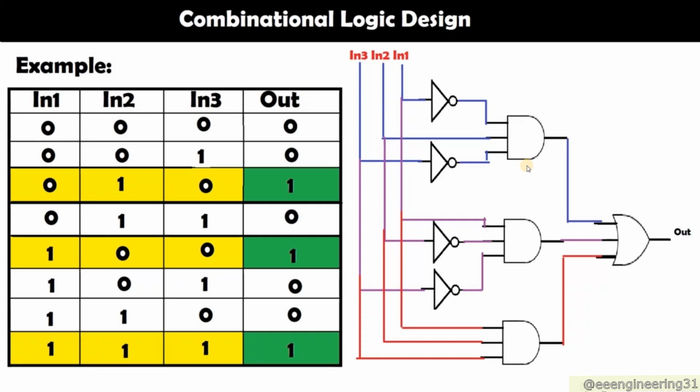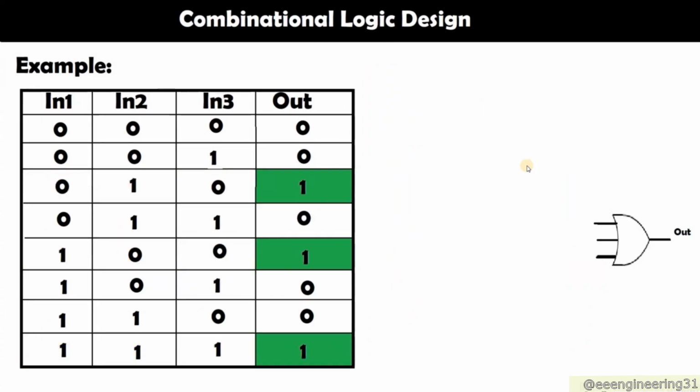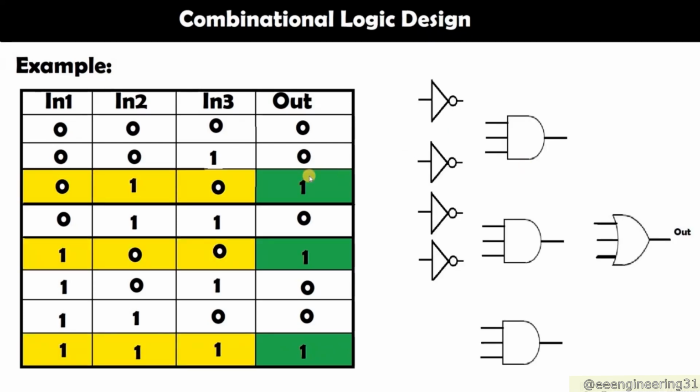So, let us sum it up one more time, really quickly. First, you identify where your 1s are at the output. We have 3 1s, meaning we have 3 options. Either of them would give me a 1. Either of them means an OR gate. Next, we check what kind of combination is going to give me each of these 1s. These kinds of combinations are AND gates.